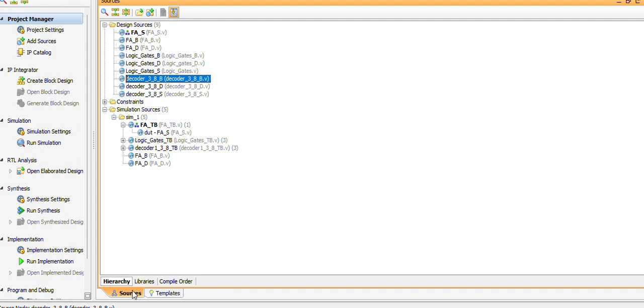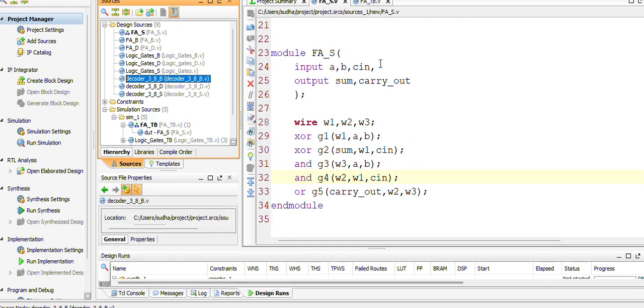So now we can see that one. So this is your Verilog code of full adder in gate level or structural modeling. Now we have to write the test bench for it. Generally, test bench will be similar for all types of circuits. Now in this case, how many inputs are there? A, B, C in. So three inputs are there. These three inputs will be initialized in the test bench.